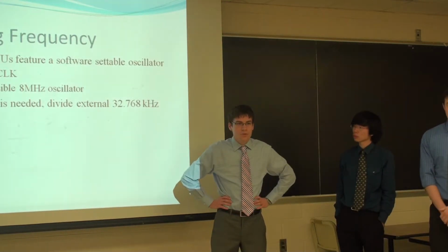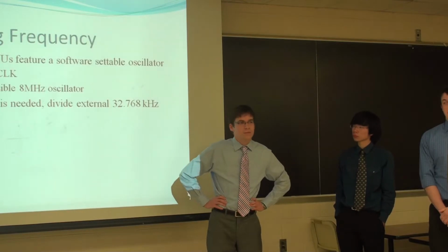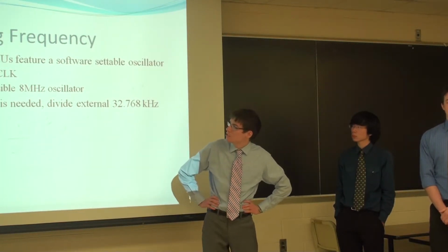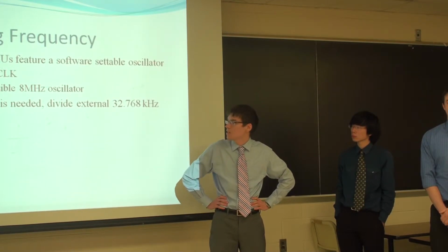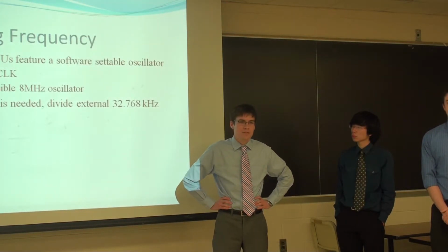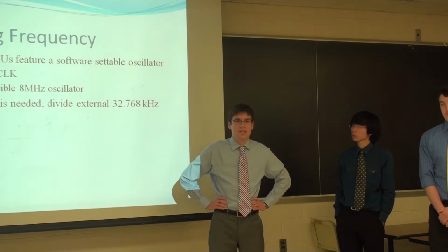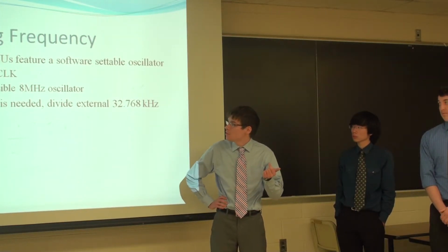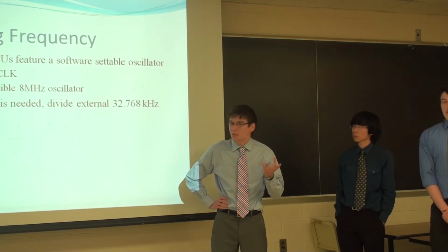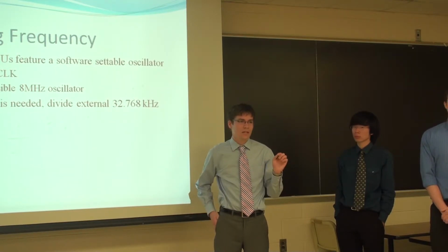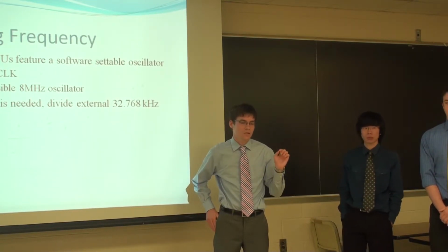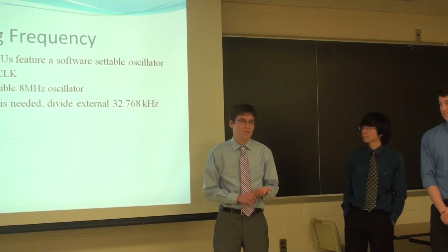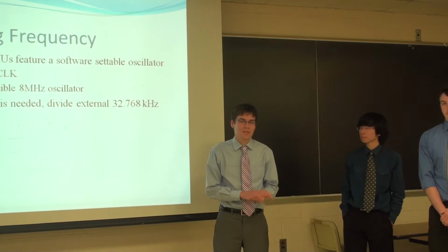So there are both software and hardware settable clocks. In the MSP430, there's a digitally controlled oscillator, or DCO clock, where you write an 8-bit value to a register, and then the clock runs at that speed. In the Arduino boards, it's a little bit different. There's just an 8 megahertz oscillator, and you write to a register to divide by powers of 2, so you can run it at 4 megahertz, 2 megahertz, 1 megahertz, etc.